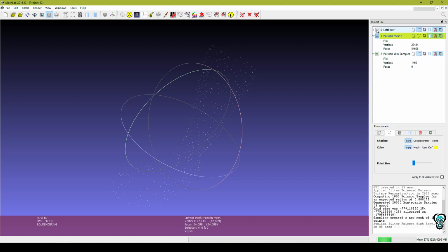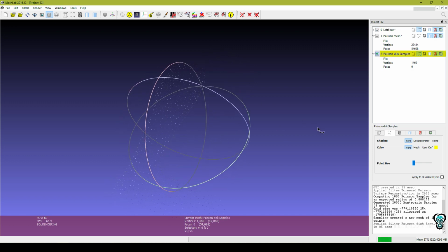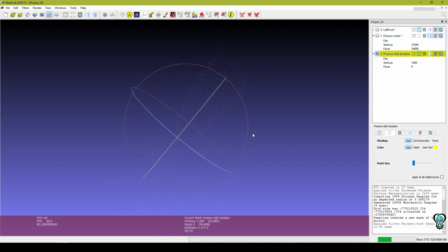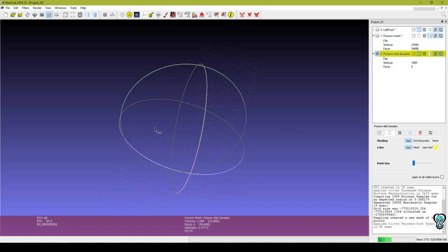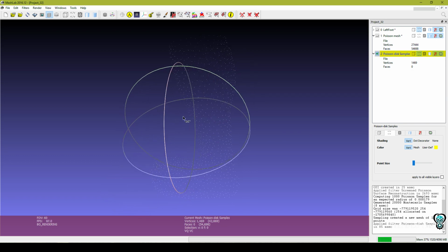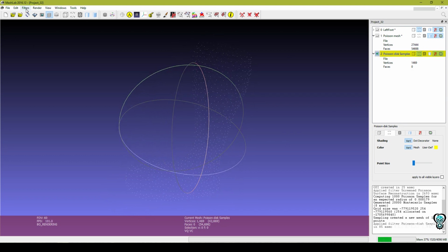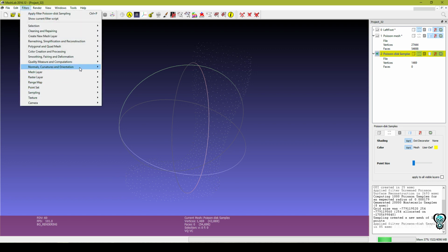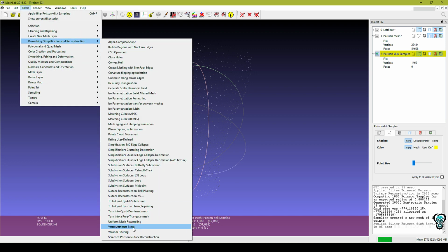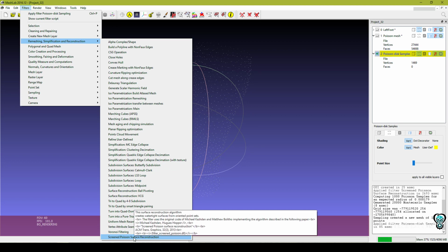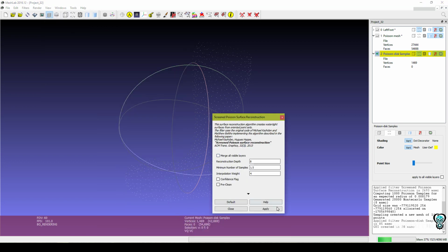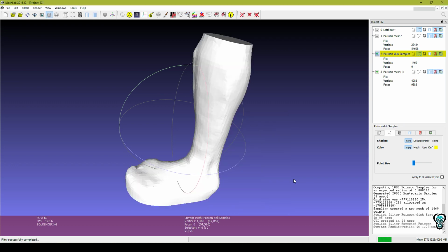The difference between them is those points are more condensed and basically the raw data, and then this is more refined, sort of captures only the necessary curvature. It does degrade the mesh a little bit. So how I'll show you here, if we go back to Filters, next step is we'll do another remesh, Screened Poisson Surface Reconstruction. Use defaults, click Apply, and then Close.